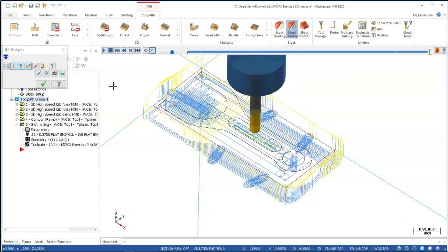Not really. If you can increase that feed rate by 20 or 30%, that extra move is nothing. Each of those extra moves is nothing if the tool is going to disengage and engage consistently in that part. So it's surprising that further into the parameters, I can increase that circle. Even though it's not engaged, maybe I increase that from the 12 or 18 or whatever I said I was going to start with.